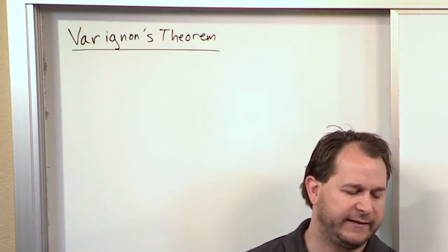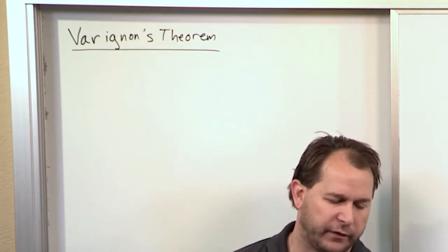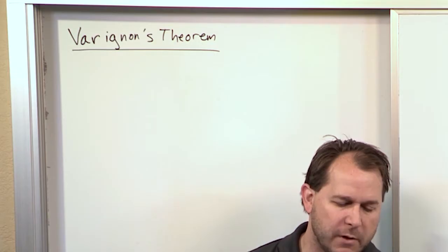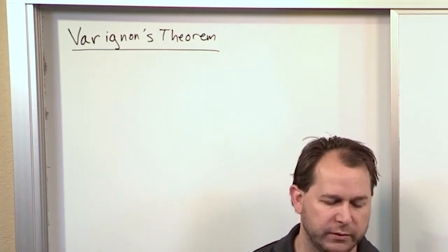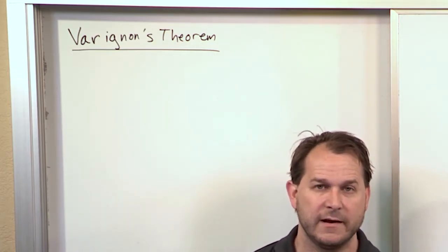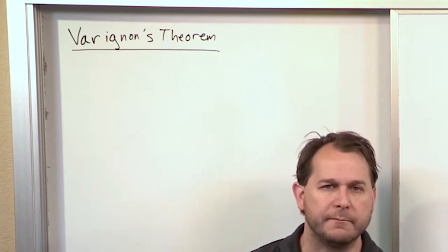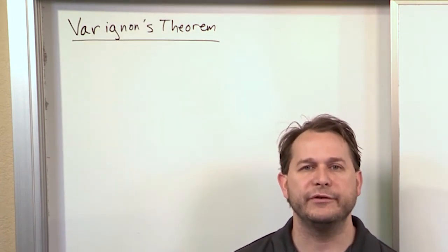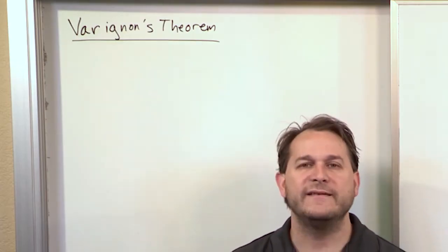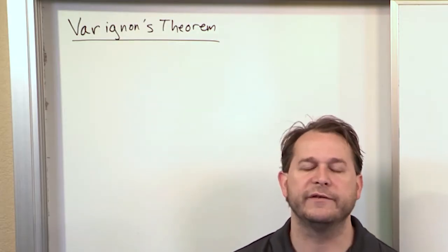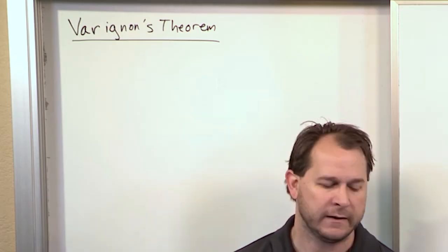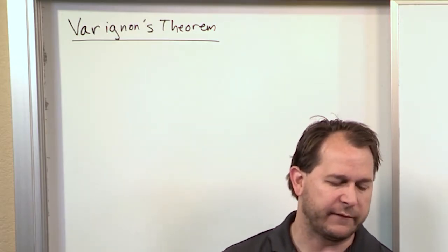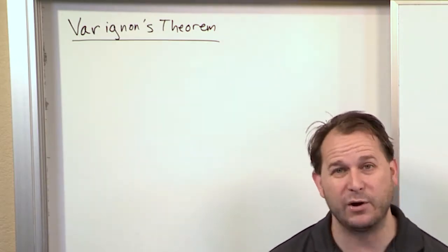The principle of moments says that the moment of a force is the sum of the moments produced by the components of the force. I'll say it again. The moment of a force produced about some point is just the sum of the moments that are produced if you take that force and decompose it into its component forces and look at the moments produced by those. So the moment of a force is the sum of the moments produced by the components of the force.